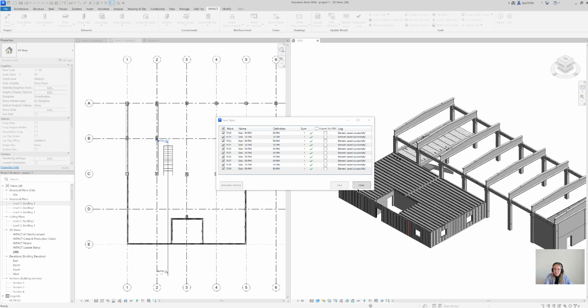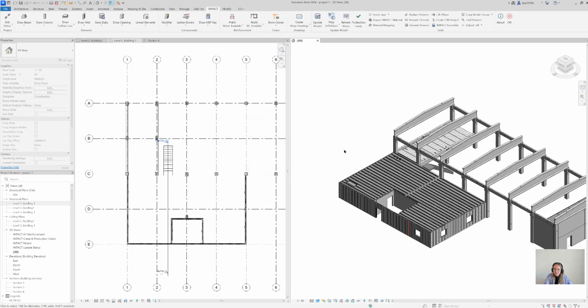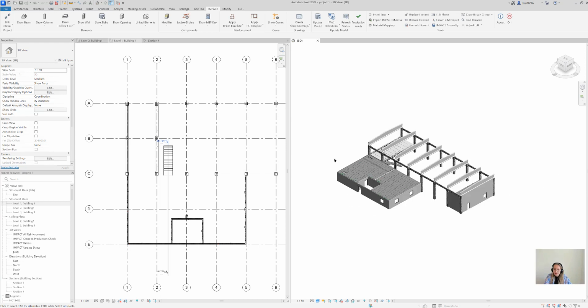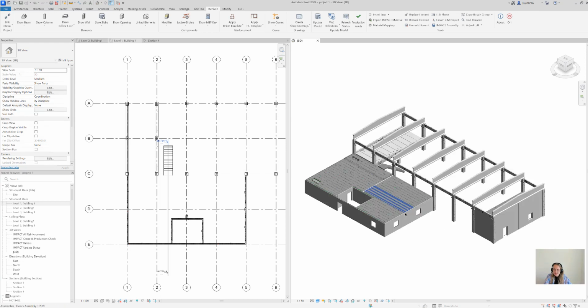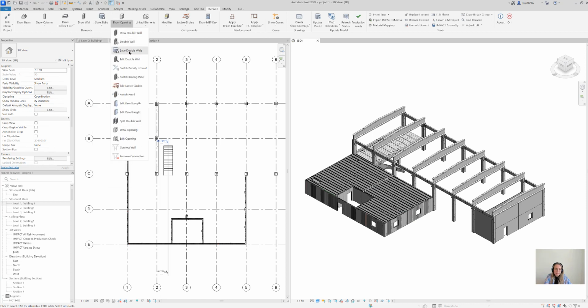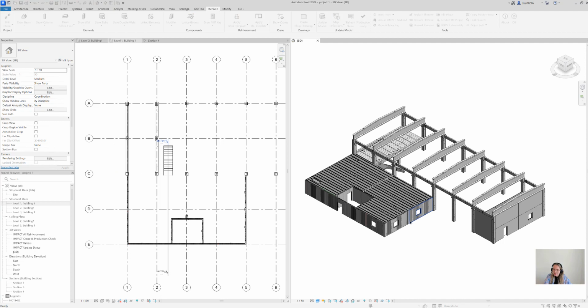Okay, we have the elements of the form slab saved, and now we go and save the double walls. We have a save double wall command, and I use the 3D as for me it's easiest to orient. What you can also do is cross select.